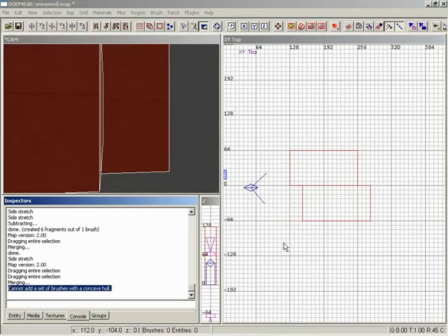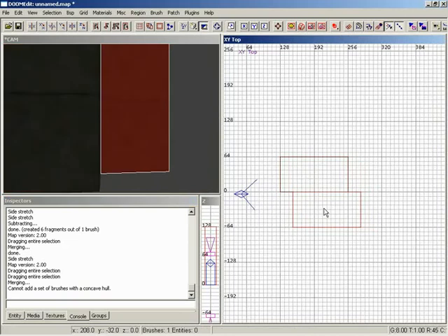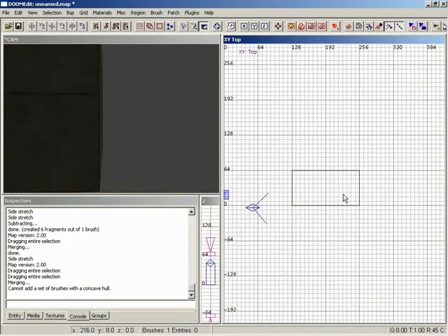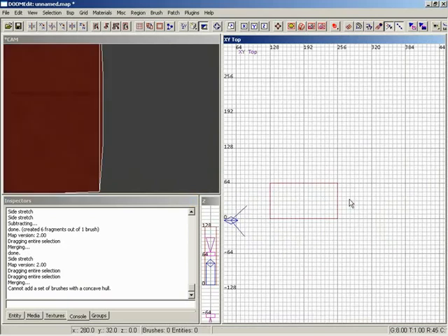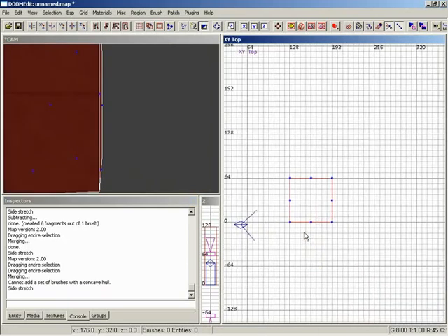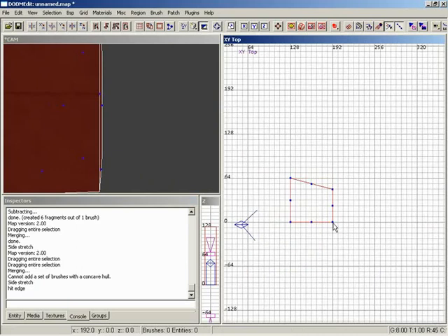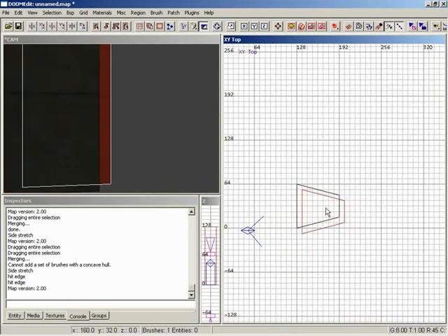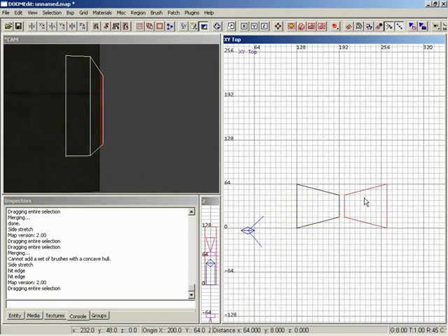So now we need to get a really good idea of exactly what constitutes a convex and a concave brush. For sure. So let me take a look at just one of these. I'll delete one out, and maybe zoom back out. Take this brush, move it in. Now I'm going to edit its edges a little bit so that I can bring this one edge in, like so. Then I'll clone that off, mirror it in X, and line it up.